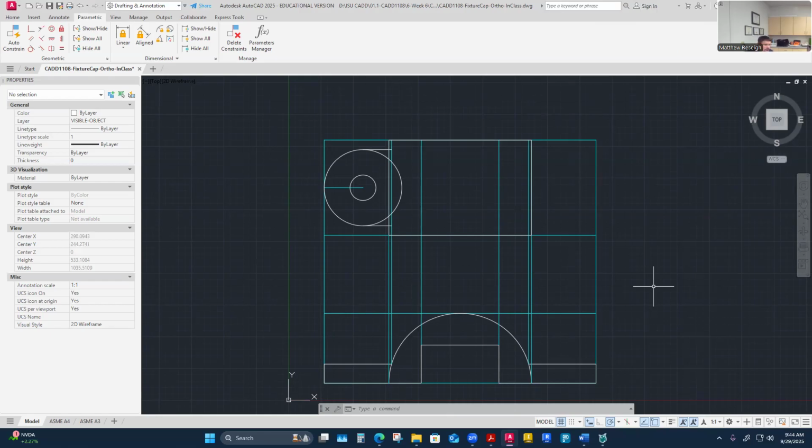And if I actually draw parametrically, I can minimize accidental movement of things. And if things really need to stay geometrically aligned and linearly the correct lengths, I can lock those in as constraints, and then it can't be moved unless I'm moving it systematically and with a purpose. So it makes it more powerful. That's parametric modeling is what it is.